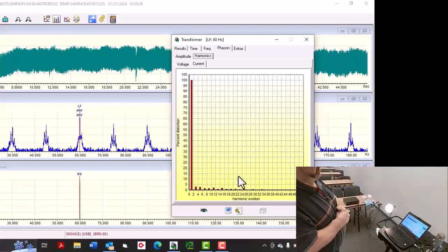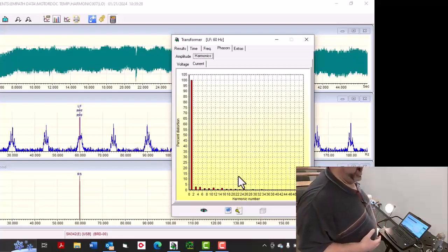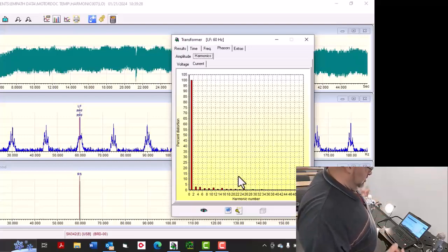It's part of the thing that we deal with when we talk about harmonic surveys, is taking a look at the entire system. It's one of the reasons why MotorDoc came up with some of our monitoring systems specifically for keeping an eye on that, because we like to measure at incoming power and what's the overall effect of any changes we make. And as a direct result, we're finding energy losses in areas we didn't expect, like ground and neutral. I mean, I've been floored. We'll just put it that way.